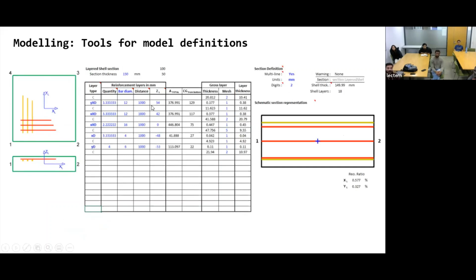And this one, the final layer shell, is kind of painful because you start stacking all the layers bottom up. So you have to define it in a proper way. For example, for every single piece of concrete, what I did at the beginning was that I didn't discretize that block of concrete. And the main problem with that was that I had sudden drops. Since all my elements were non-linear, that sudden drop was really, really hard to solve, and I had a lot of convergence issues.